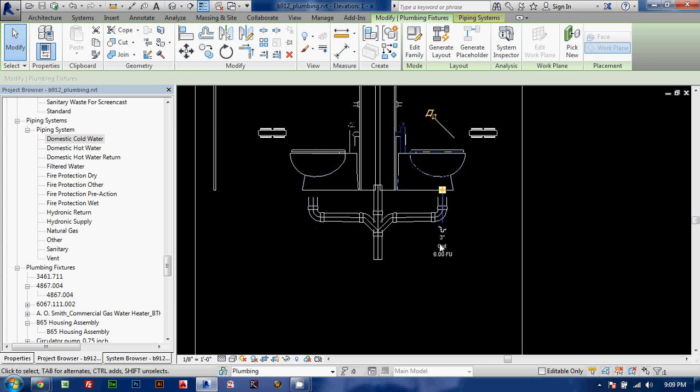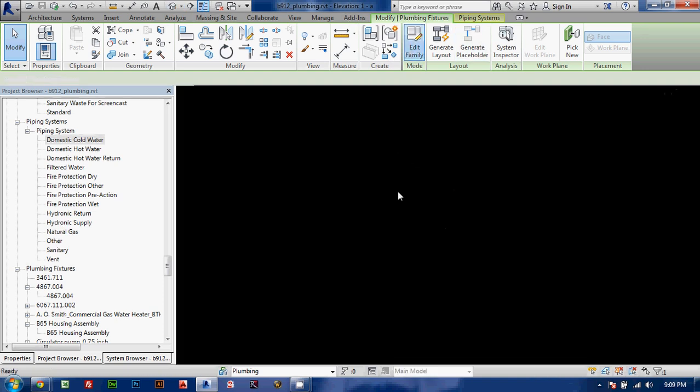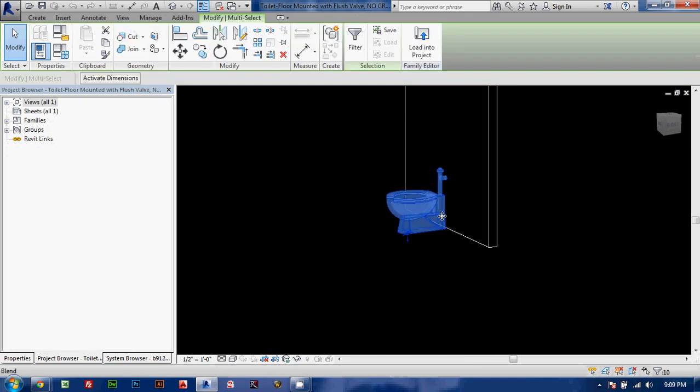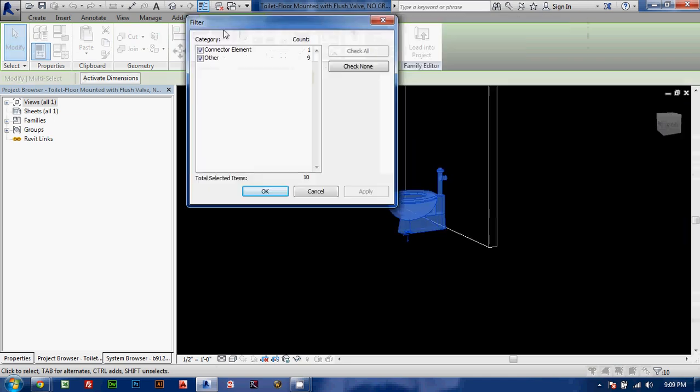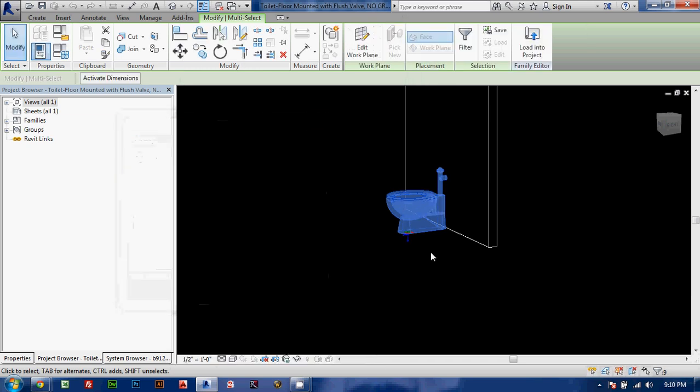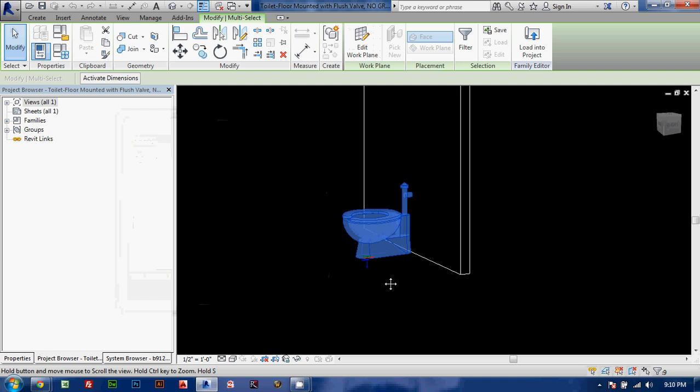And there's a couple of ideas I've been throwing around, and I'll show you this on other screencasts as a better way, I think, to deal with these. But just quickly, I'll give you a glimpse of what that's going to look like. I'm going to select this family. I'm actually going to select all of this. I'm selecting everything because I am very confident with this filter feature of Revit. I don't want to select the connector element. I want everything except for the connector element.